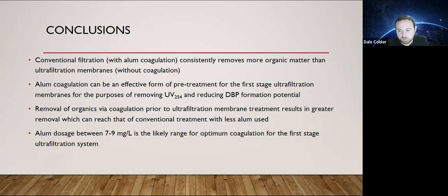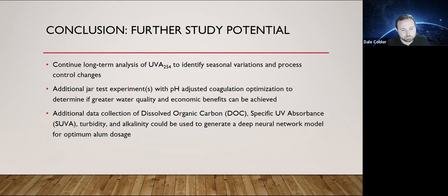An additional benefit is that this could be accomplished with less alum dosing than the conventional treatment process, and it includes recycling of spent filter backwash water. The True water treatment plant could continue to optimize the alum coagulation process by collecting and analyzing more relevant data. This could result in additional organic matter removal and potential cost savings.